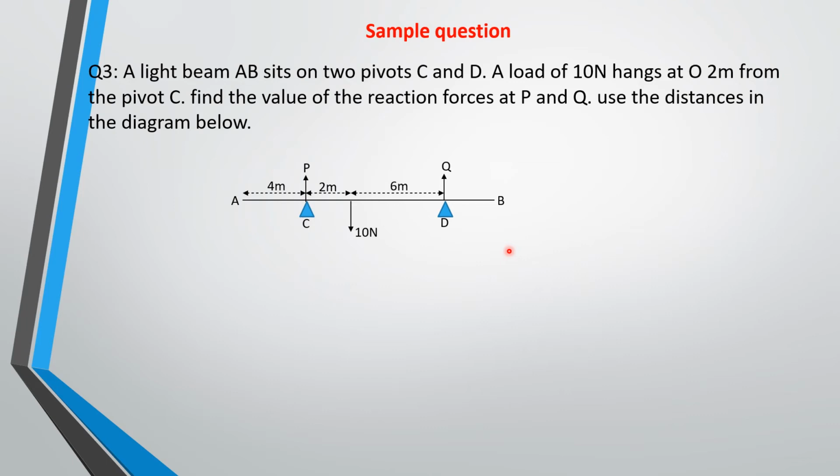I decided I need to solve some more problems on moment, because I know it's always a challenge to students. In this particular instance, remember when we said that upward force is equal to downward force, or that the force in one direction is equal to the forces in the opposite direction. That is the first statement that you make when you see a question where you have 2 points of suspension for your meter rule or for your weight, because these are reaction forces.